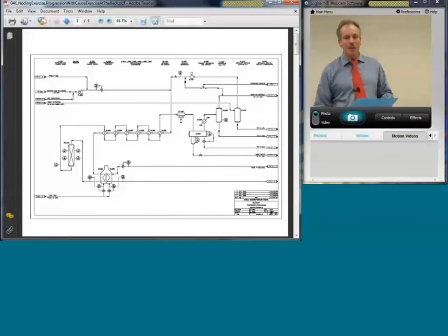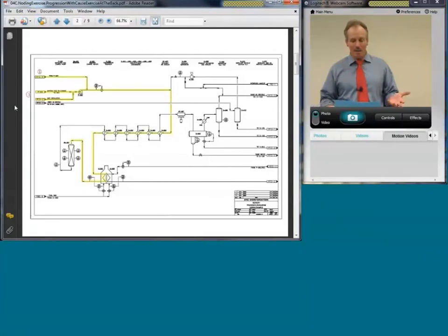So what I would do with this in terms of defining the nodes, and that's what you see on your screen now in yellow, is take the feed coming in from the upper left-hand side on flow control, going through your heat exchangers that economize the heat from the reactor effluent, and then to heater 001, and then to the inlet of the reactor.